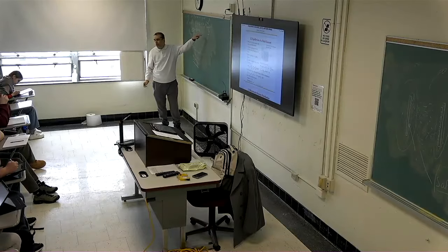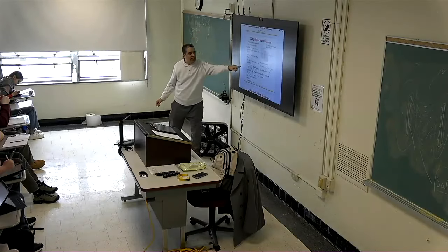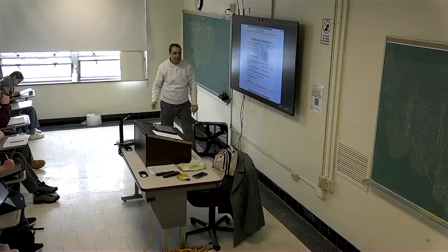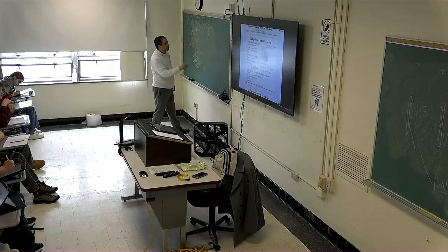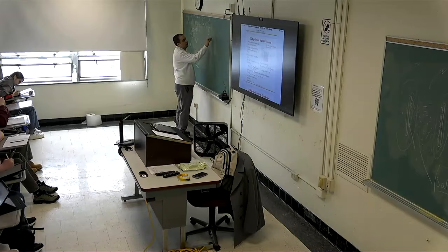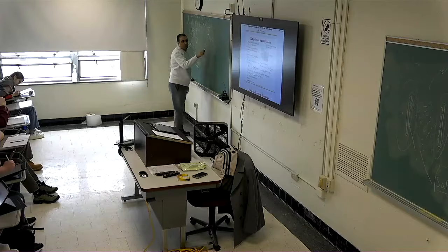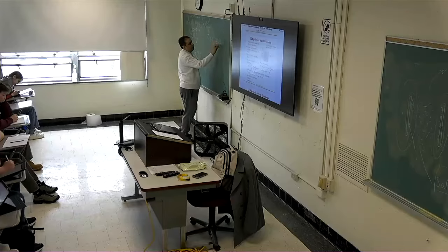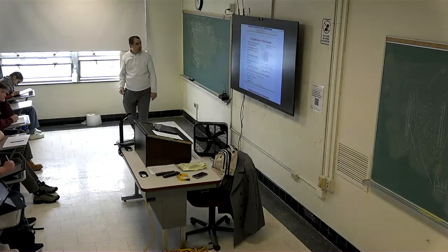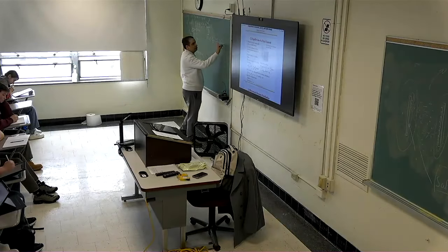When I put a vector sign, or in your book, a bold sign, it is a vector. dF is equal to minus partial p partial x i, minus partial p partial y j, minus partial p partial z k. This is the pressure force, multiplied by dx dy dz.